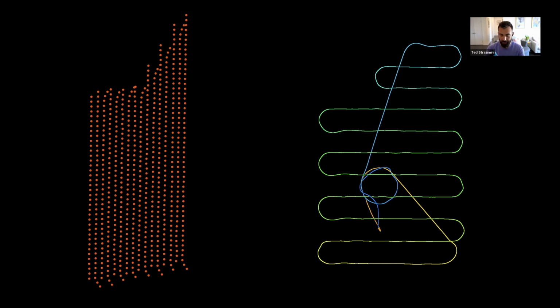You can also notice that there's a few parts in that trajectory that are not mapping portions, right? That's the aircraft taking off and transiting to its first waypoint. But overall, it is very similar. Big difference, though, in efficiency. You don't need to do 75% overlap, for example. You can get away with much, much less, like 30 or 40%, and that allows you to cover a large area very quickly.